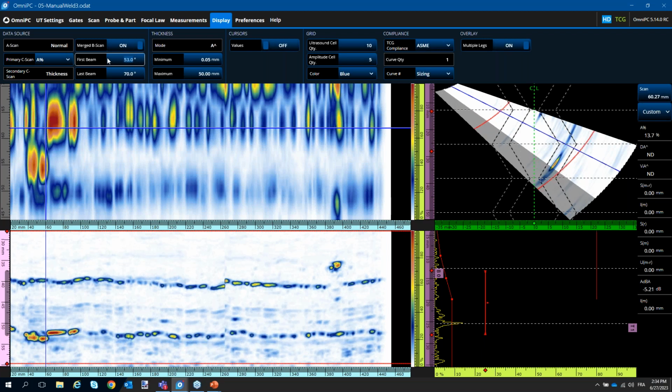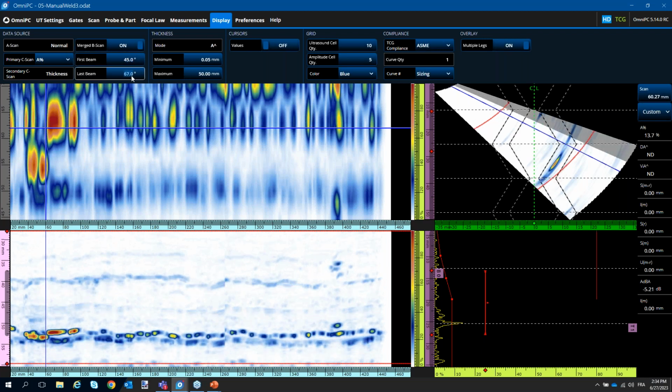Or if you have this as a recurring pattern in the weld, you may want to use that for your streaming also. But keep in mind the angles that you're hiding, because you're basically hiding a portion of useful angles more than likely. So you have to make sure you're not hiding defects by doing so, like I would if I were using this too heavily.